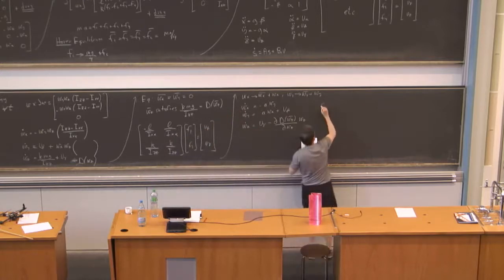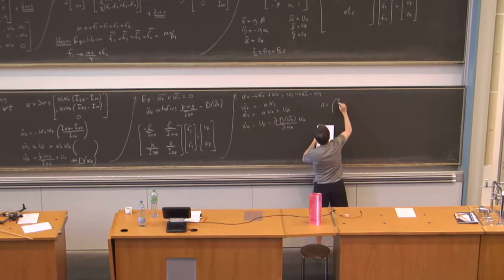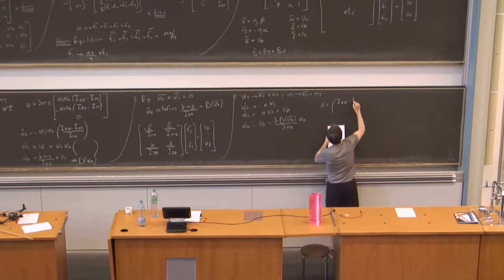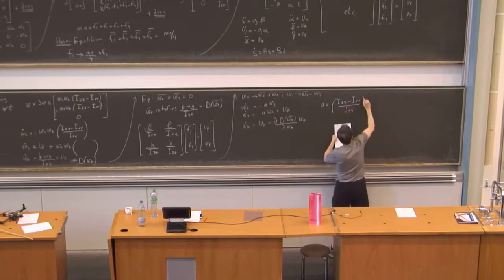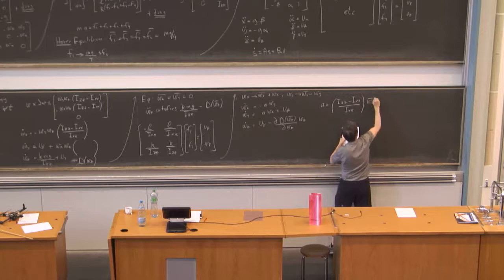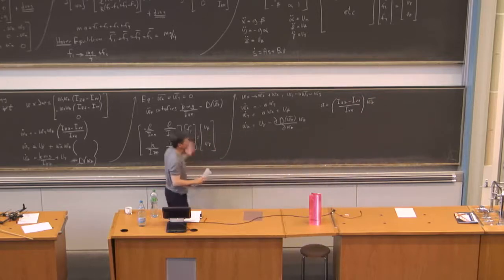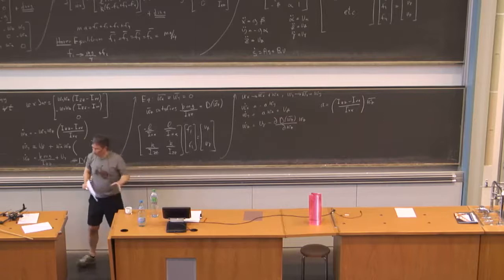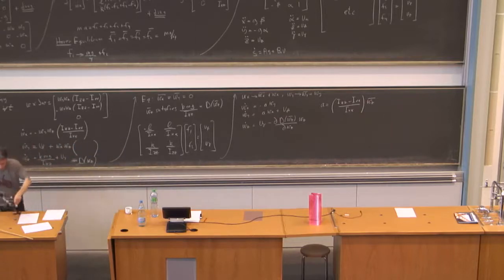And what is this A? A is equal to Izz minus Ixx over Ixx times the equilibrium speed, rotation rate, wz bar. Okay, it's just simple substitutions. Okay, so we're almost there. What we care about, as I said, is the direction of the normal in inertial space if I want to control where this thing flies. So I want to be able to couple this analysis to how does my normal change as a function of omega x and omega sub y.